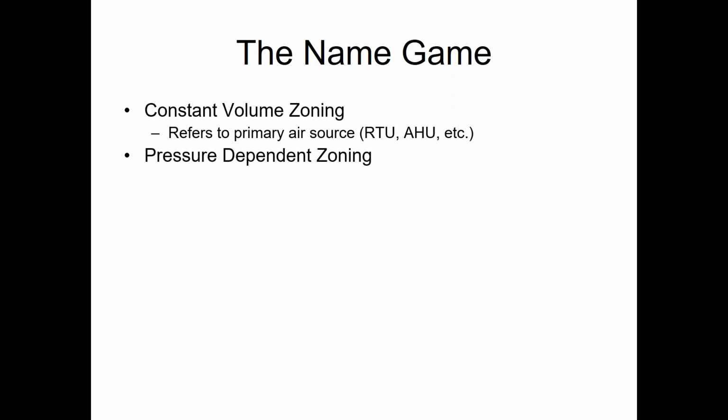So what that means is that the individual VAV box has its airflow monitoring station at the inlet to the VAV box, and it's going to get its desired CFM for that moment, no matter what the air handler does. If the air handler provides more or less airflow, the damper will react and change its position to get the same amount of CFM that it wants. So if it wants 278 CFM, it's going to modulate to get 278 CFM independent of what the air handler is doing.